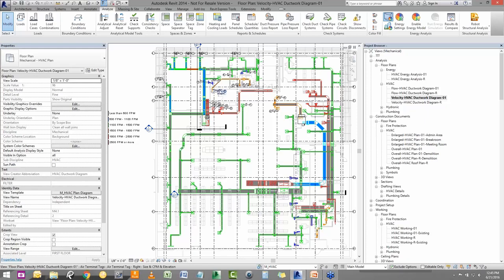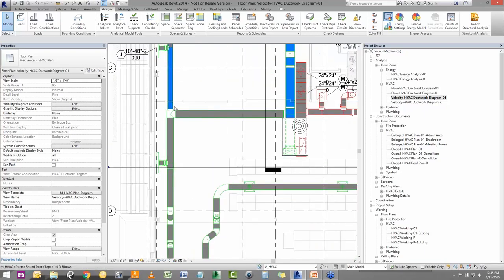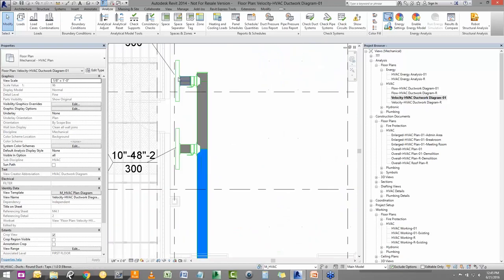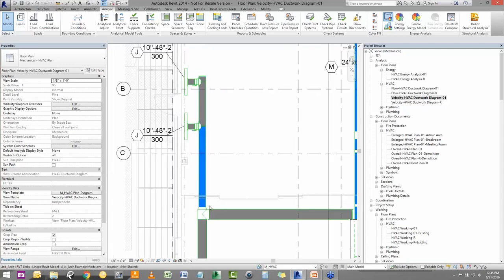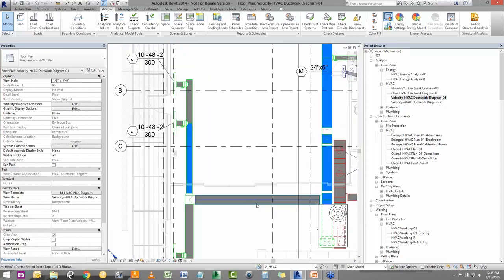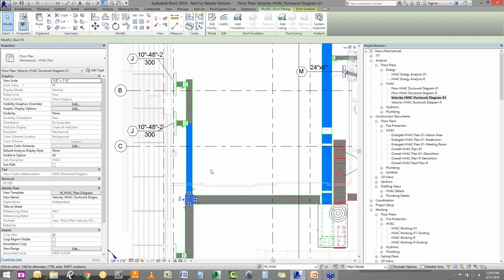As flow goes as well, it's also important to remember that fittings are data collection points, and ductwork and or pipe for that matter are transfer points. So the data would actually be coming backwards. It comes from the diffuser, and travels down this piece of ductwork, is gathered by the takeoff, then travels down this piece of ductwork, gathered by this takeoff, travels again, and is gathered by this T-fitting here, and then again sent down.